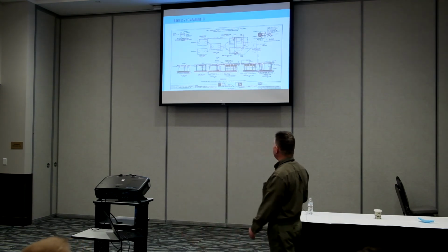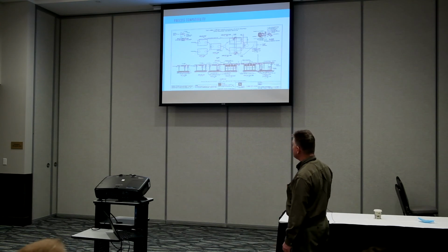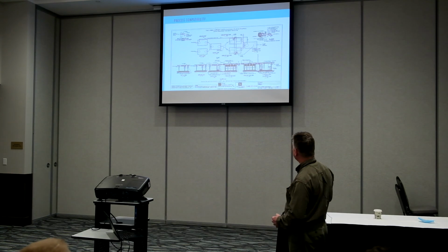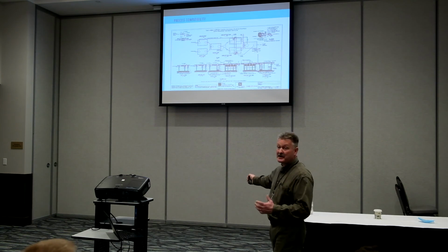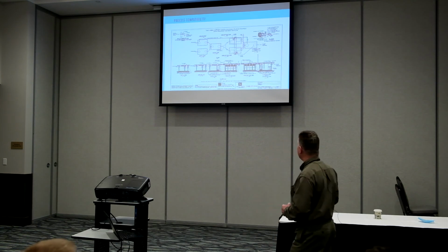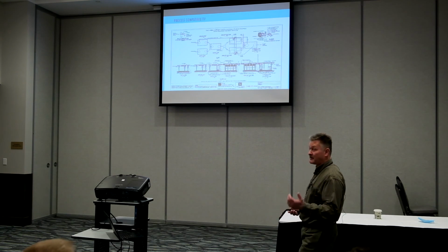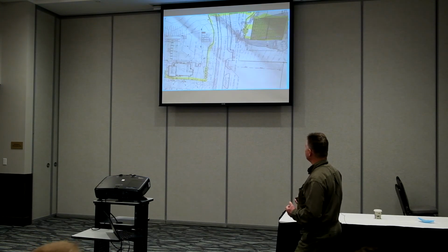So this is a typical process that you might have on a commercial system. Again, a lot of components involved. We're going to have grease tanks, septic tanks, a flow equalization tank, in this particular case a couple different aeration units, a clarifier, and if we need to polish even more, we may have another secondary treatment system included. So a little bit more complex, and we really need to get a good handle on our characteristics to produce that design.